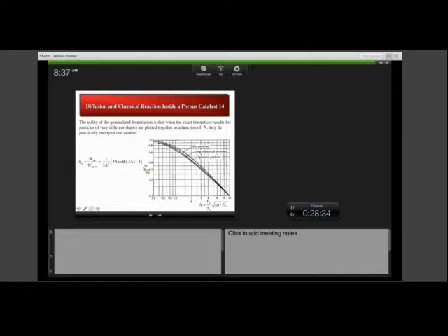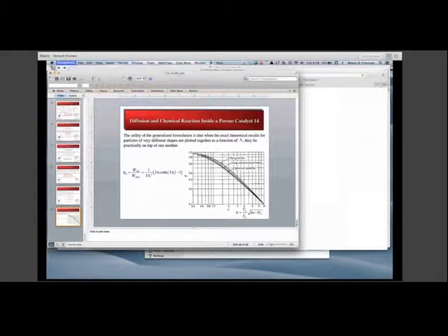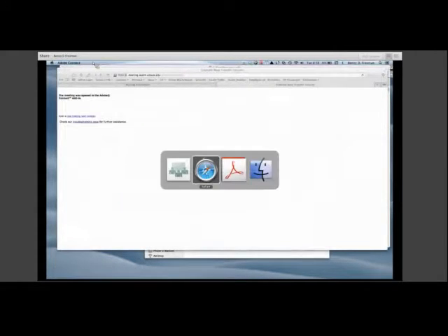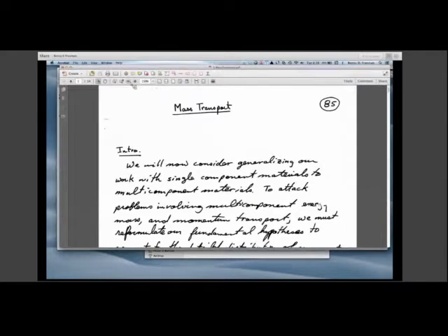And if you then plot the effectiveness factor as shown here versus the generalized Thiele modulus, the results for spherical particles, long cylindrical particles, and flat particles lie on almost the same line. And you can see that as the Thiele modulus gets large, that is, as the reaction rate constant gets high or the diffusion coefficient gets low, the reaction becomes starved.